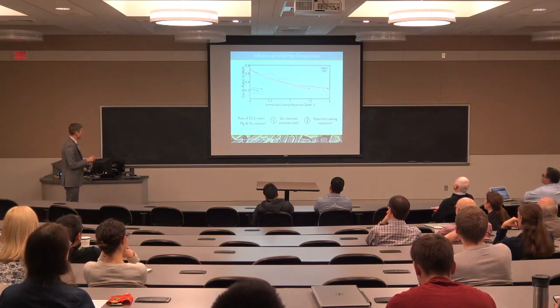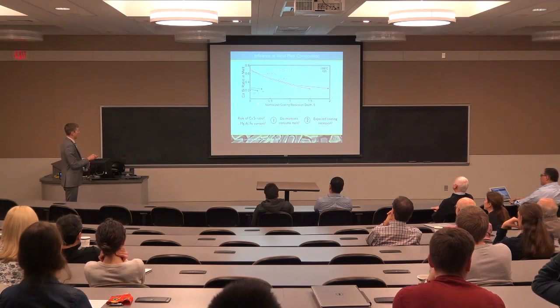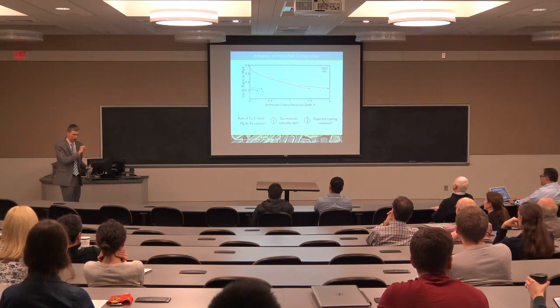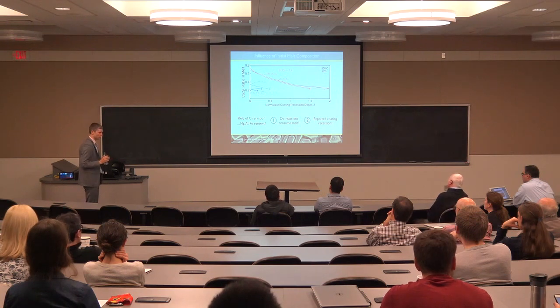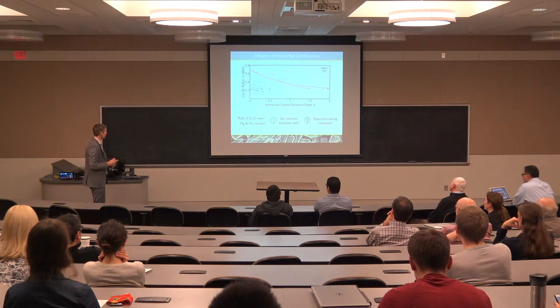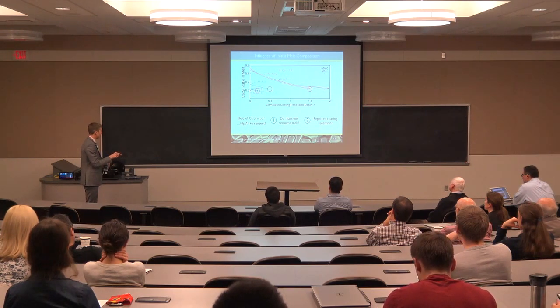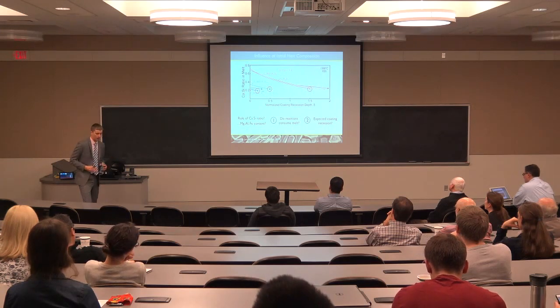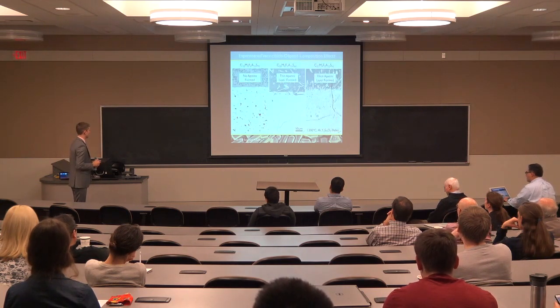If we instead pick a family of very calcium-lean melts, there's not enough calcium to promote much apatite formation, and our expected maximum recession depths are very small. So we might lose a little bit of the coating, but not very much. And then we can fill in between and find that while there is variation within each of these groups, the calcium-silicon ratio in the deposit is an important factor. We can pick out a few of these, maybe one that shows almost no recession and one that shows a lot of this detrimental reaction or recession process, to verify this experimentally.